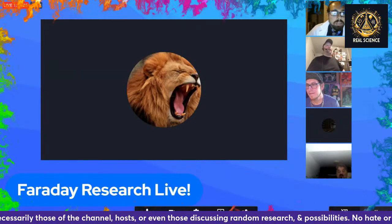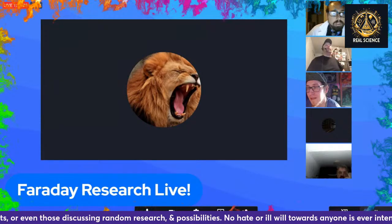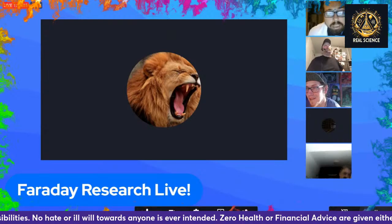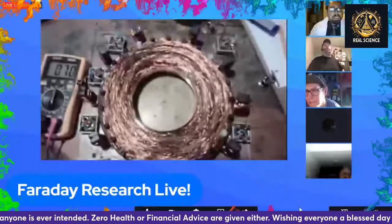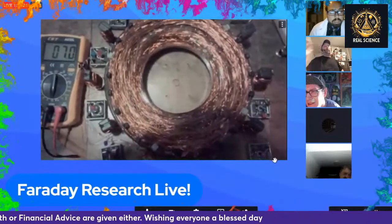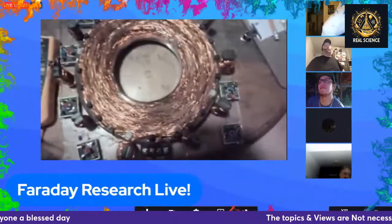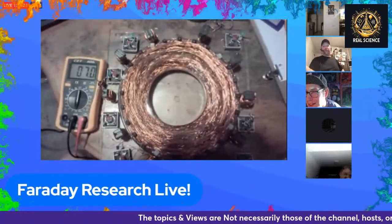How many times did you wind that one? Oh, Gerald. Yeah, that coil was 750 feet one way and 750 feet the other way. Jesus, that's a big one. Bifilar. Yeah, I spent some time on that. 22 on the primary, 23 on the secondary, or maybe reverse that. I'd have to look at my notes. It's been a while.